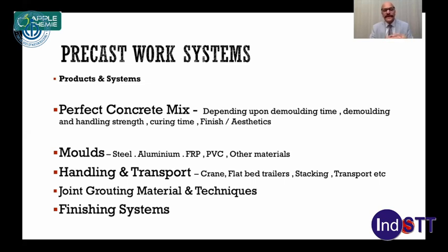And the third aspect when you design concrete is what finish you want after the concrete comes out of the mold. That is the aesthetics and the finish. So you can have various molds, and on the molds you can have so many designs, inlays, or texturing, so that the final product has that look. Coming to the molds where the precast concrete is put in, you can have molds in steel, aluminum, FRP, PVC, and many other materials also.